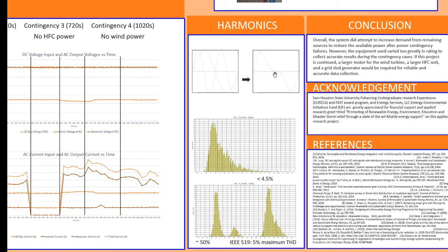The early CFL light bulbs, the compact fluorescent ones, the early ones that were made more cheaply, they did not have filtering required to remove these harmonics. And so because the current was fluctuating so much, it would cause house fires actually. So harmonics are not something you really want necessarily.